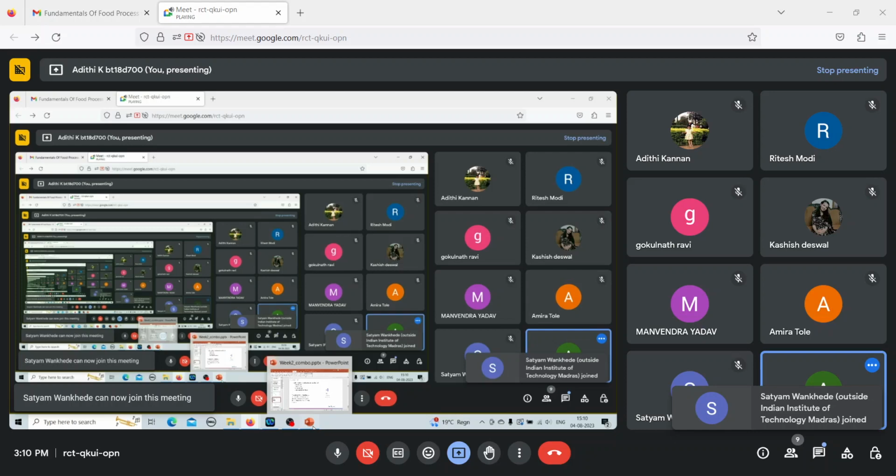But when you come to statement 2, the upper plate is circular and rotating while the strain is offered to the liquid which is kept between the plates. This is false because you are not offering strain. The top plate rotating results in a shear. You are offering stress, and it results in a shear stress. That's the difference. You are trying to maintain a certain shear stress and you are not offering a shear strain. Hence statement 2 is false. The answer is option C. Is this clear, how a parallel plate viscometer works?